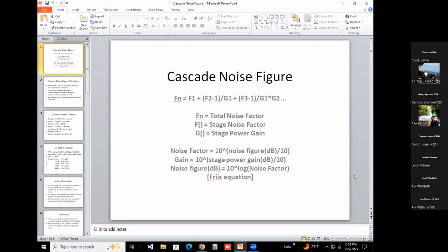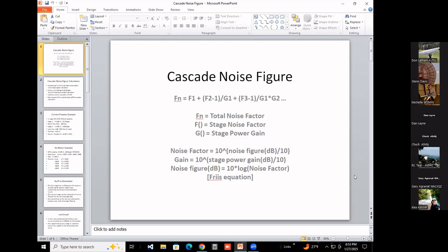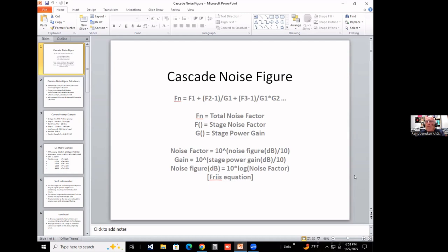But quite often the comments arise about how we do the preamps down at the site. And a preamp here, I'm referring to something that is extra from a regular radio. It's something that you mount up at the feed antenna, so there's very little loss in front of the front stage. I'm going to go over the equation a little bit, talk about that for a few minutes, and then I'll give you some examples and where to get the equation, where to get a calculator for it.